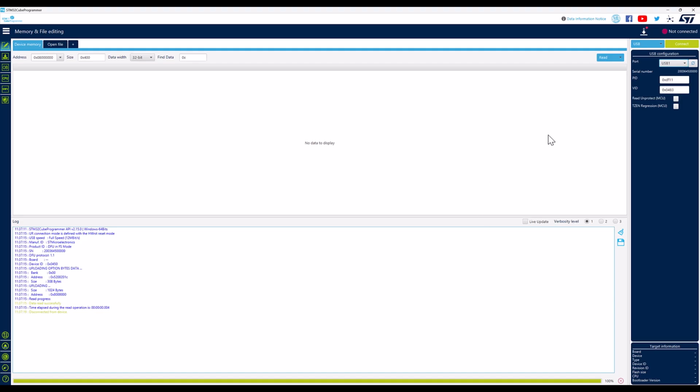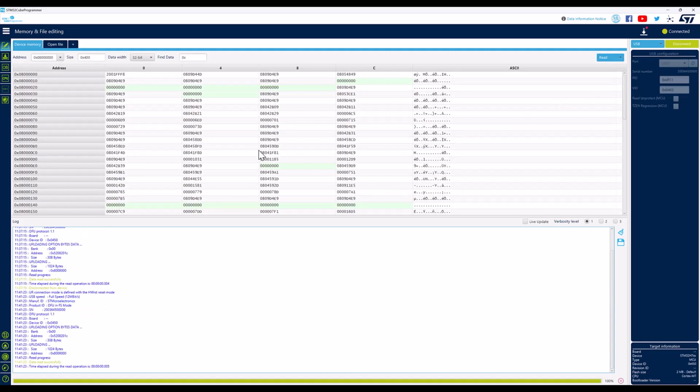If you open STM32 Programmer and find that there is at least one USB device connected to your computer and it was recognized, because if we disconnect this drone, it's going to be an empty field here, we can click the connect button. And this tool will read everything that is on the microcontroller.